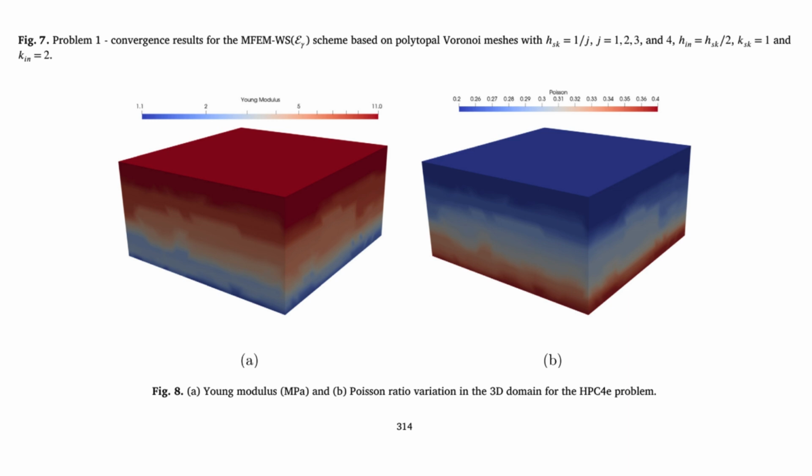That's the beauty. Once you've solved the small global system for the tractions on the boundaries, that traction information becomes the boundary condition for independent problems inside each polyhedron. Independent, so each block can be solved on its own. Completely independently. These are local Neumann problems. You solve for the secondary variables, the detailed internal stress, displacement, and that rotation variable within each block, using the globally computed traction as input. And because they're independent, you can solve them all at the same time, in parallel. Precisely. That's the massive win for efficiency.